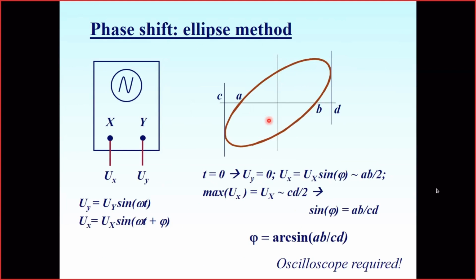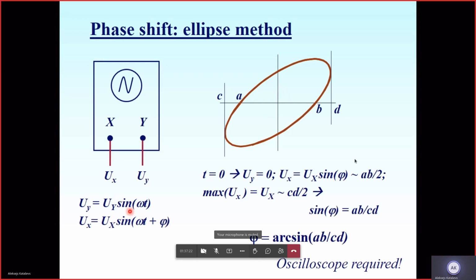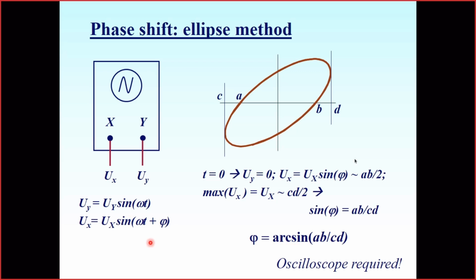The smallest teeny differences in the frequencies actually cause a constant phase shift between one signal and another. We could write that the frequency of the measured signal is omega, but the generator shows omega plus some small delta omega, which is very small.